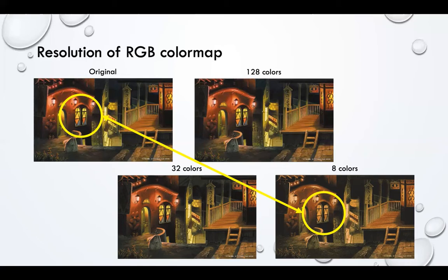You can use the interpolate function in the Matlab library to refine the color map. Otherwise, you will lose some resolution or lose some colors in your figures. Here I don't list the command because it belongs to the image processing spatial library.